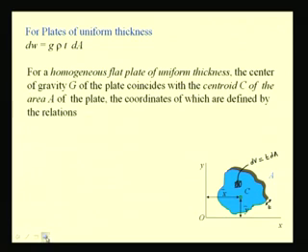And if we compute those quantities, we will find that if other things remain constant, that is, it is a homogeneous material, so rho is constant and gravity is also constant, and it is a thin plate or a uniform plate, then T is constant. Then we will see that the centroid C of this area coincides with the center of gravity and center of mass of this plate.